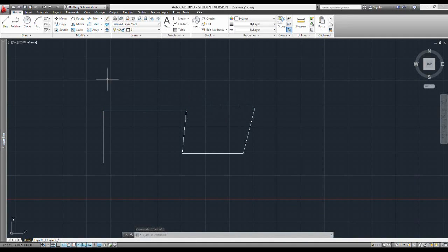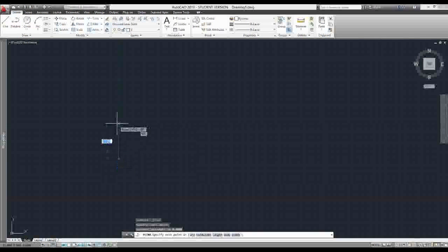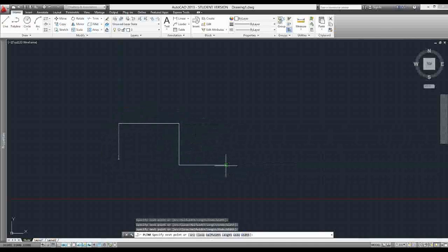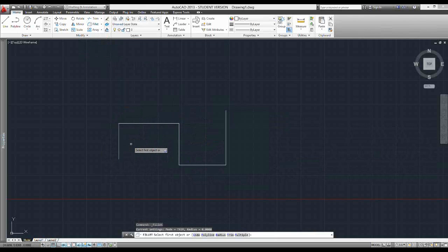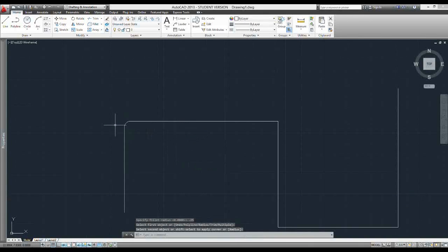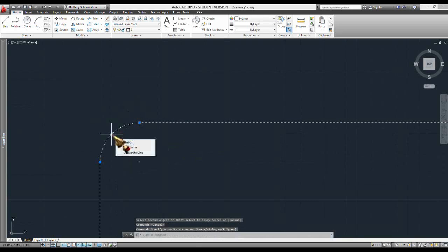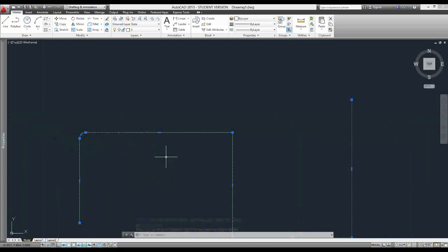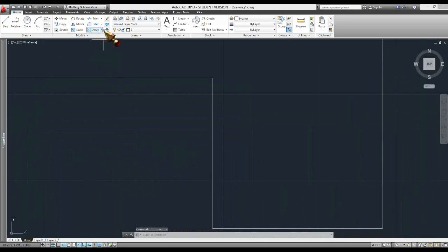And that's pretty much all I have about polylines. Perhaps one thing, though, that I could mention, okay, is fillets and chamfers on a polyline. Probably wouldn't be too bad. Okay. If I have fillet, okay, I'm going to give it a small radius here, 1/4 inch. I'm just guessing, so we'll see. I fillet that. It adds an arc to the actual polyline. If I select the polyline, I've got an arc in there. Okay. Using the chamfer or fillet commands will not break the polyline.